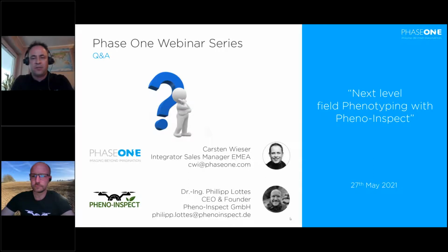We have an integration for the DJI M600, and we have lots of customers and partners building drones on Pixhawk based platforms with the MAVLink protocol. This is an interfacing language we can use, and our camera knows how to combine the camera into the drone and communicate with the camera from the ground station. So you have full control over the imagery during the flight. You see the results, you get some feedback. You can change shutter speed, aperture, and so on.